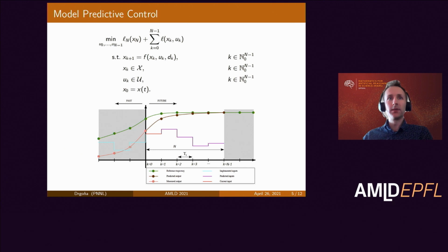So what do we think of model predictive control? We formulate it as the following optimal control problem, where you have some performance objective, be it reference tracking or energy minimization, and you want to find the optimal trajectories of your control actions subject to the constraints of your system dynamics model, which is typically designed by hand from first principles or obtained by system identification, and constraints on your state trajectories and input trajectories.